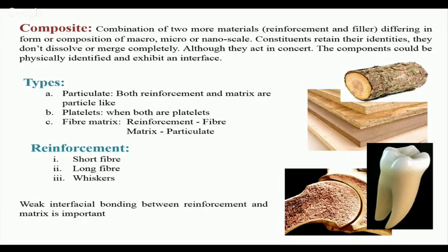I think one of the finest examples is, as we know, in India we make a lot of idols of clay. Even clay houses we make. While making the clay houses, we mix jute, straw, chopped into small fibers, with the clay, and then we cast. So this is one example where fibers hold either side, and if there is a crack formation, the crack doesn't propagate. Here fibers act like a bridge between the two sides.